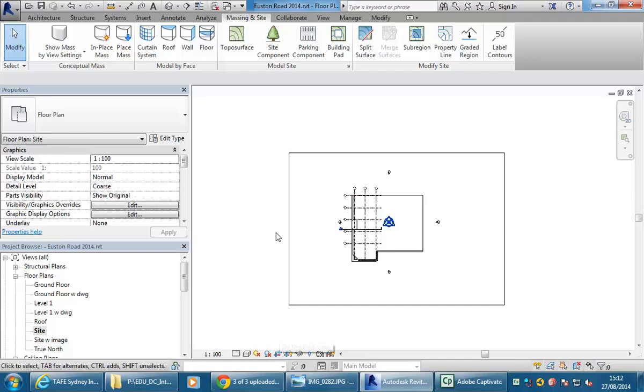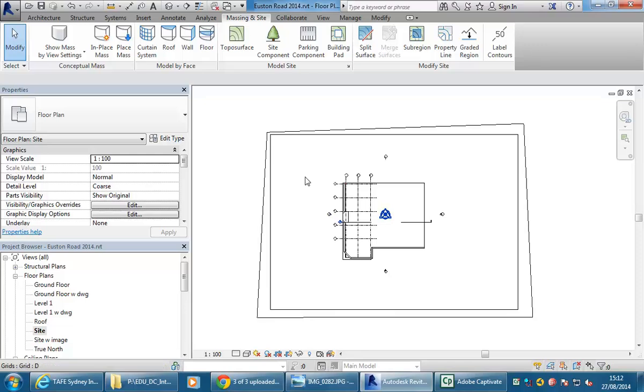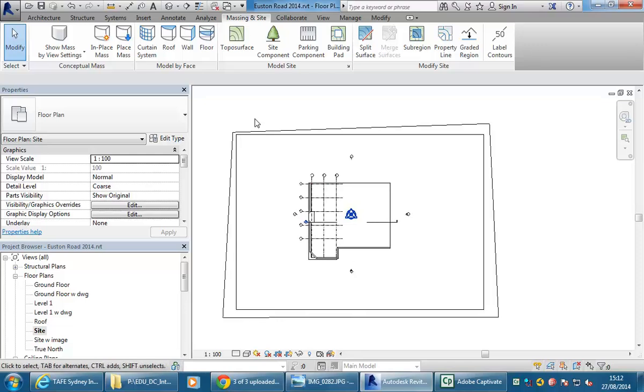Another good trick there, if you want to see the side edge again, you can just disable cropping. It'll leave the border there, but it'll show you what's around it. And what happens if you render it like that? It'll render with the ground now.